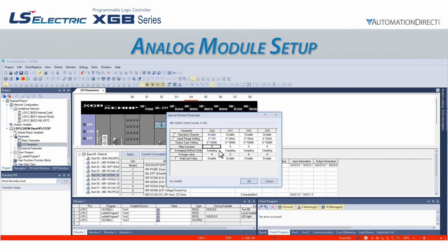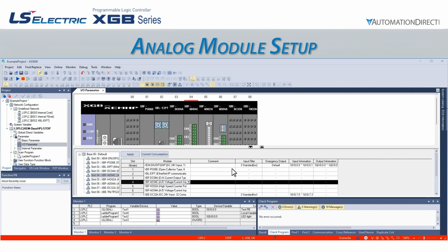The filter constant, averaging method, and hold last value functions all vary significantly based on the analog input module used. They have to do with how the module cleans up the input signal, outputs it to the PLC CPU, and what the module does in the event of invalid signal input. Please refer to the documentation and help files for your model for more details on each. Once we have configured these functions, we can select OK. Please note this only changes the settings in the software. We will need to write the project to the PLC for the changes to be sent to the CPU.